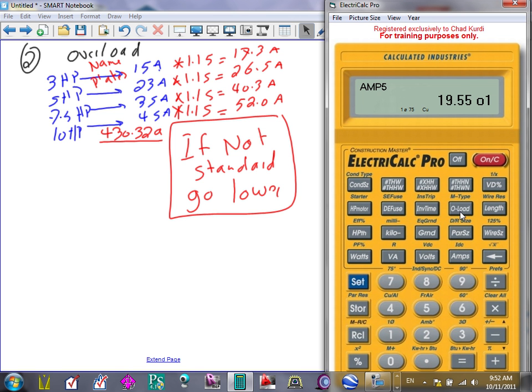So let me try to cheat it though. Let's say we know the full load amp. Can you guys see 15 and force a 15 amp on it? Just put 15 amps, force it on it. I haven't tried that one. Let's see if we can get 17. Yep. I can force it to take the full load amp. Or if I don't know, sometimes we have no idea what the nameplate says yet. You can use the default from the code.